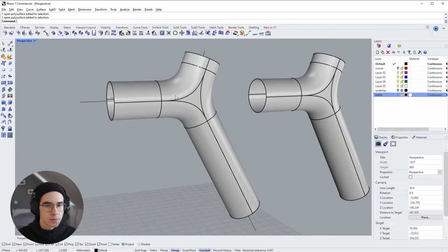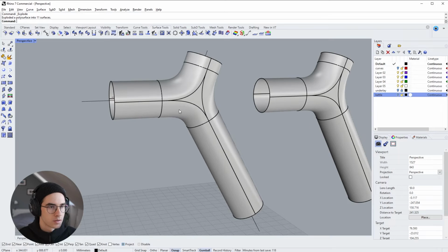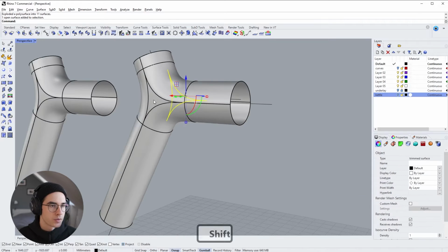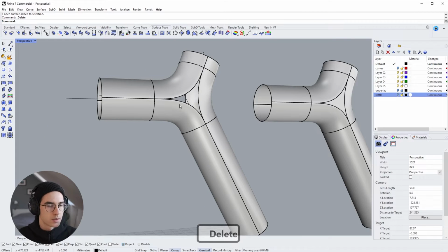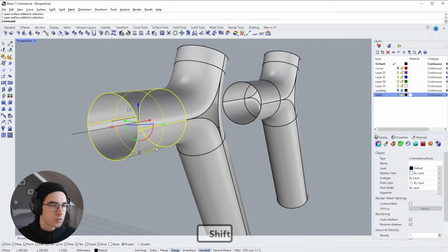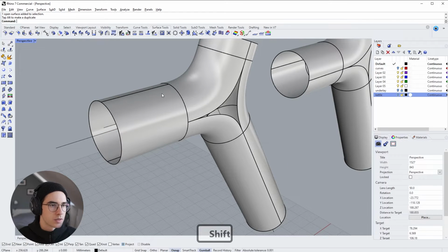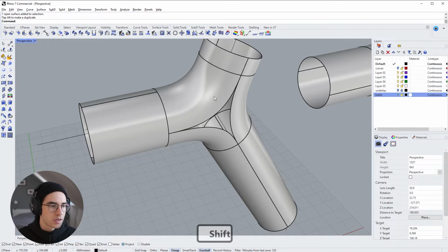This approach won't work perfectly, I can tell you now, but we'll have a third one that's also possible to use. First, I'm going to explode these into their separate surfaces. Then I'm going to delete those inner parts. We don't need those. Next, we still need the halves, but we need to rotate them 90 degrees so the splits are along the x-axis.